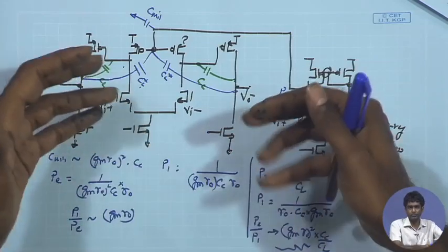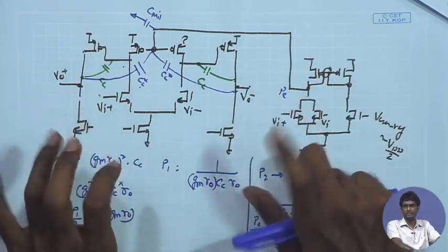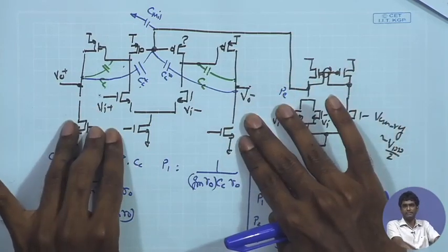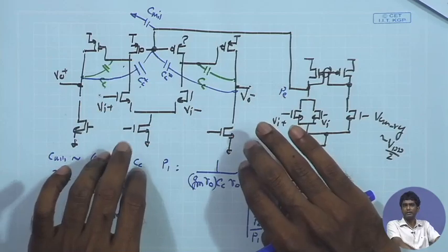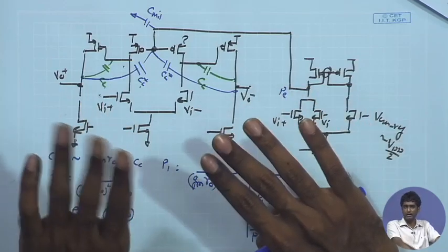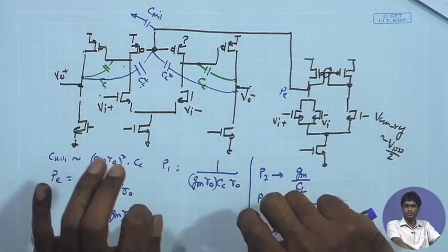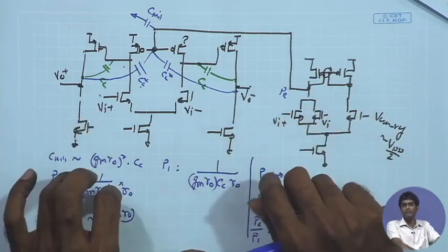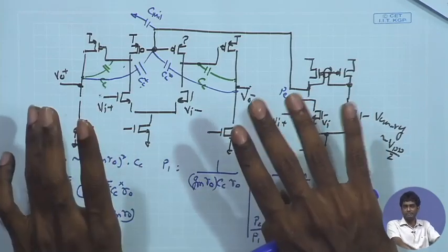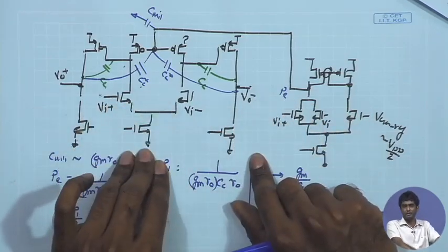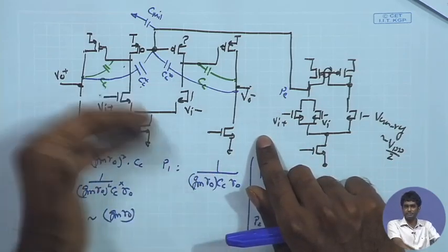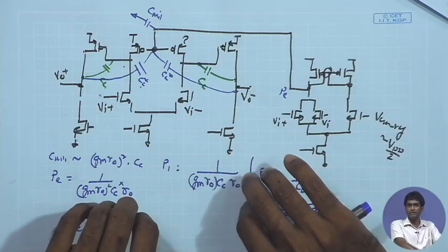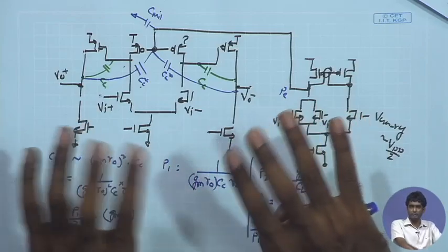It just gives you a starting point, if you have estimates of the device parameters, or you have the values of the device parameters given from the technology, like the K and Kp of the MOSFET, the noise parameters of the MOSFET, the lambda value of the MOSFET. Even if you can estimate these parameters, in the second order model we use just lambda VDS, and that lambda is not explicitly mentioned in the higher order models. It depends on many other parameters.